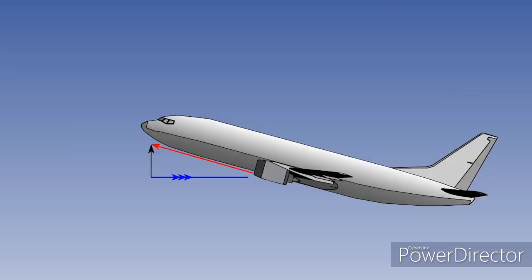A typical jet aircraft does not experience the induced flow velocities of prop-driven aircraft, the only significant factor being the vertical component of thrust. This means that, since less lift is required to support the aircraft, there is lift in hand to decelerate to a lower speed. The effect on stall speed at high thrust can be large, but since there is no induced flow, the angle of attack at the stall will be very similar to that of a power-off stall. The conclusion for both categories of aircraft is that power on stall speed is less than power off.